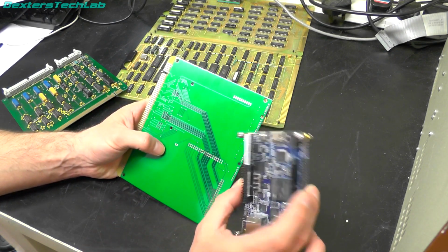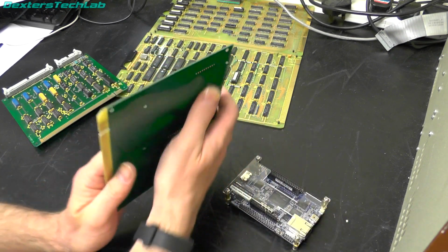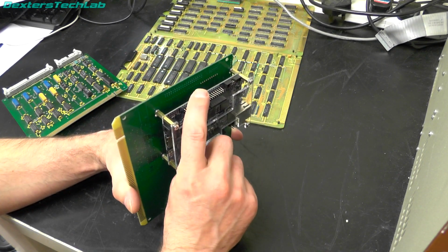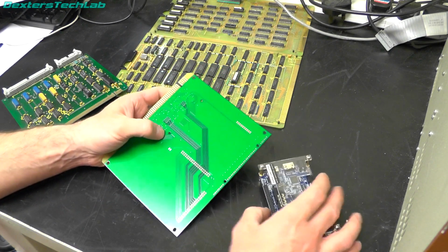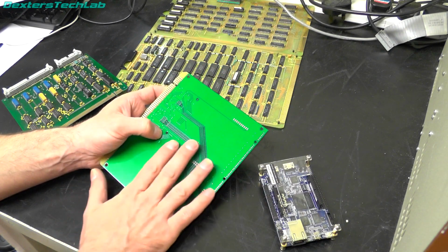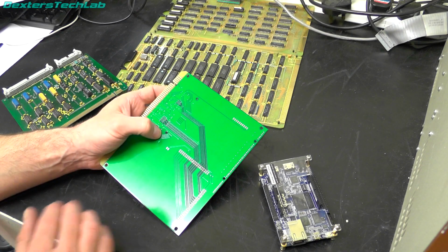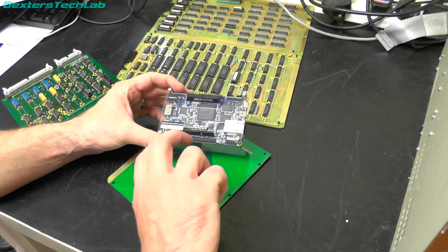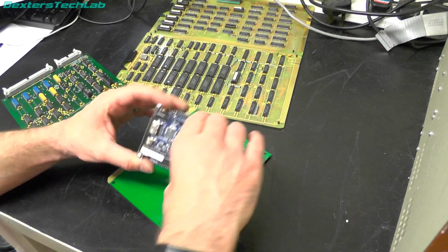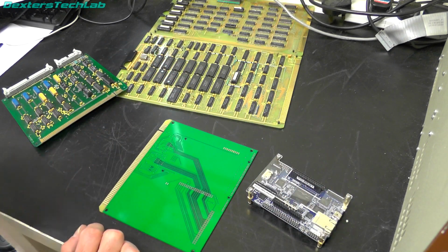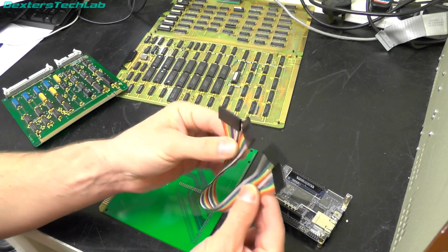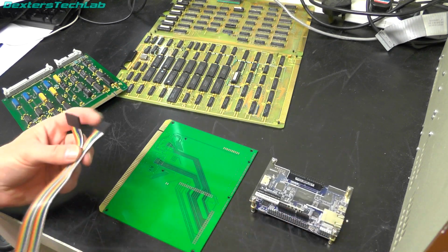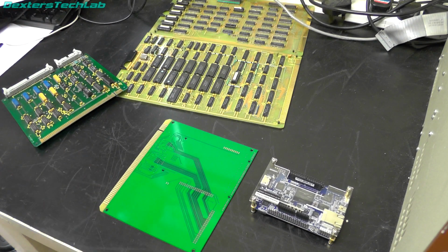What we're going to do is actually mount this on the other side, so this will still plug in that way. The DE10 will go on there like it was before, but just on the other side, and we'll come down to a pin header on here. Because this has been swapped over, everything's mirrored, but that means we can't just have a ribbon cable now, because if we twisted it round, you'd also swap top to bottom. So I think what we're probably going to do is I'm going to make up some cables like this, so I can separate the two rows of the connection pins, just so we can connect it onto this side easily.